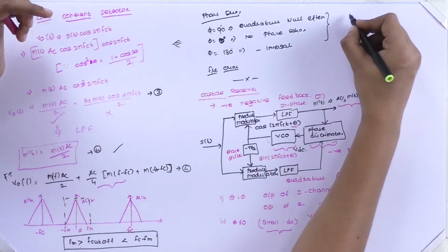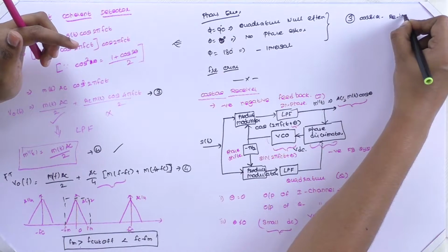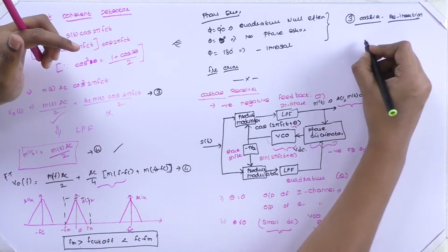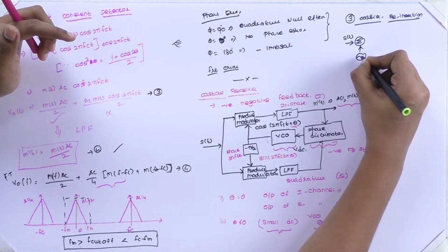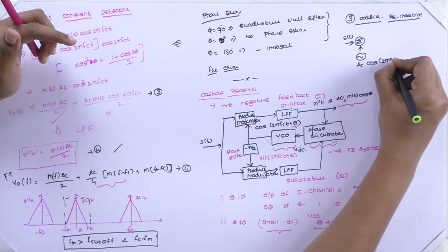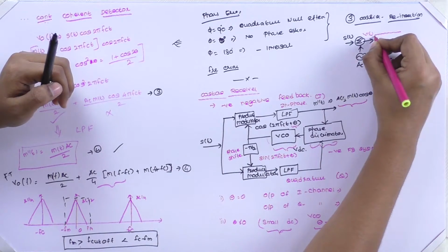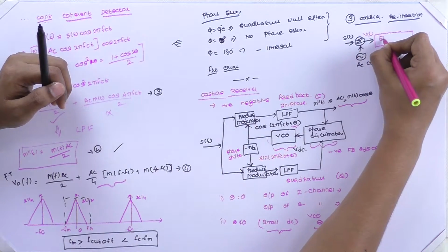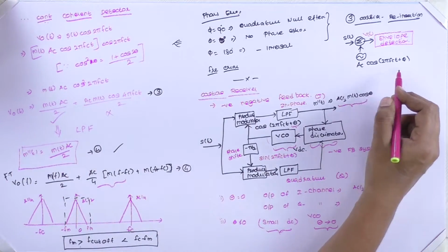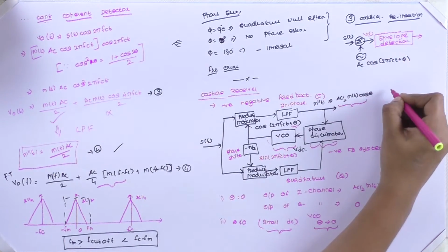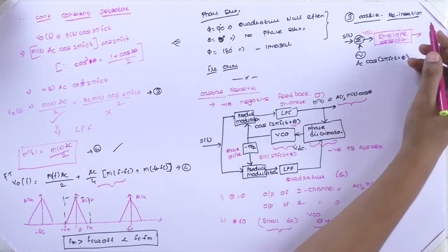The third demodulation technique we are going to see is the carrier reinsertion technique, or envelope non-coherent detector. Here we apply s(t) and the oscillator A_c cos(2 pi f_c t + phi). The resultant signal v(t) is applied to the envelope detector. We refer to this as the carrier reinsertion technique because the envelope detector just follows the AM envelope. We are inserting the carrier and then suppressing it at the output of the envelope detector.